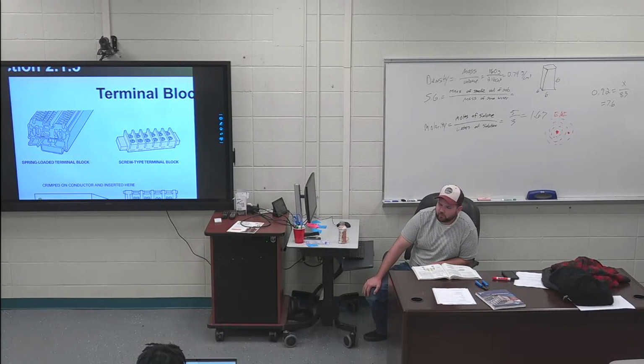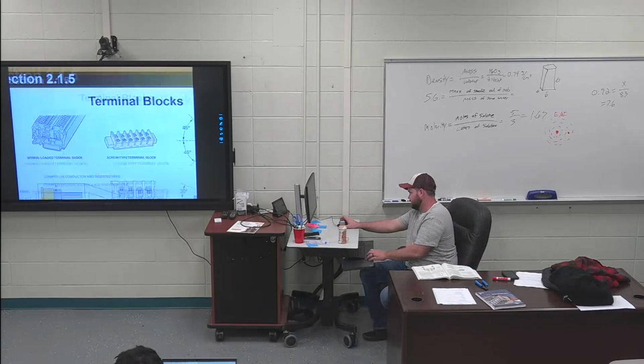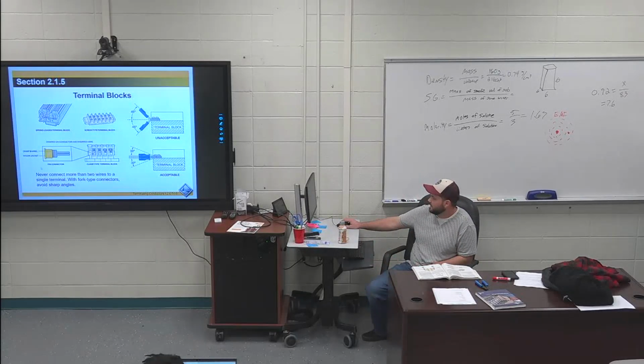You can't shove 5 wires in a termination point. I'm sure everybody will see it done. Don't do it. So like you can have pin connectors. It's always nice to have pin connectors and stuff like that, but I wouldn't get used to it because you don't see them that often. But typical screw block termination, I can only throw 2 conductors in each terminal spot.